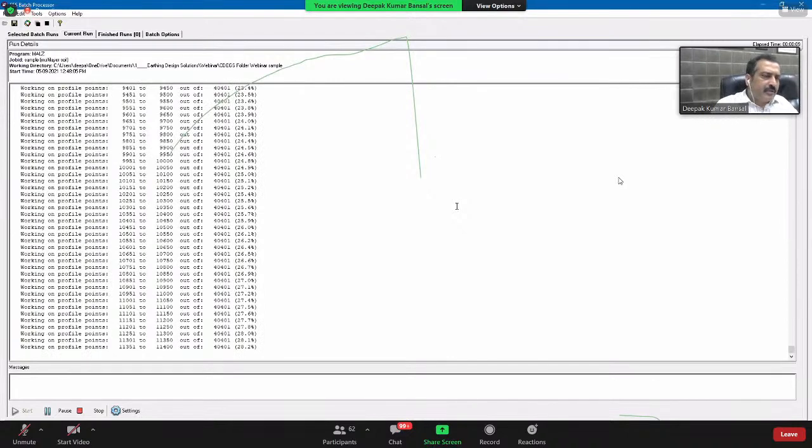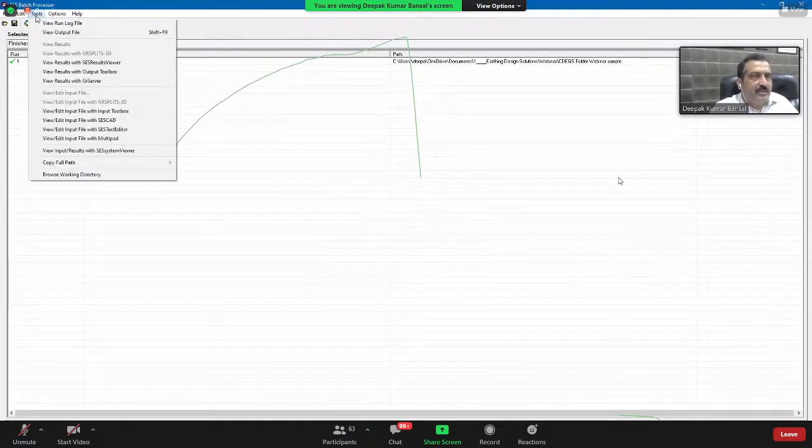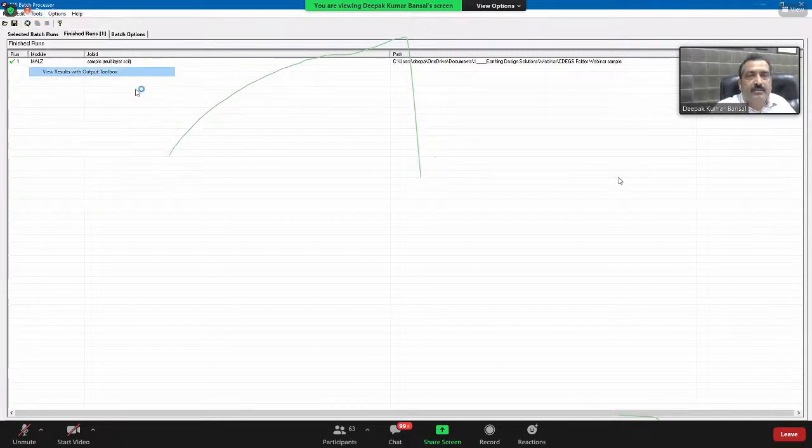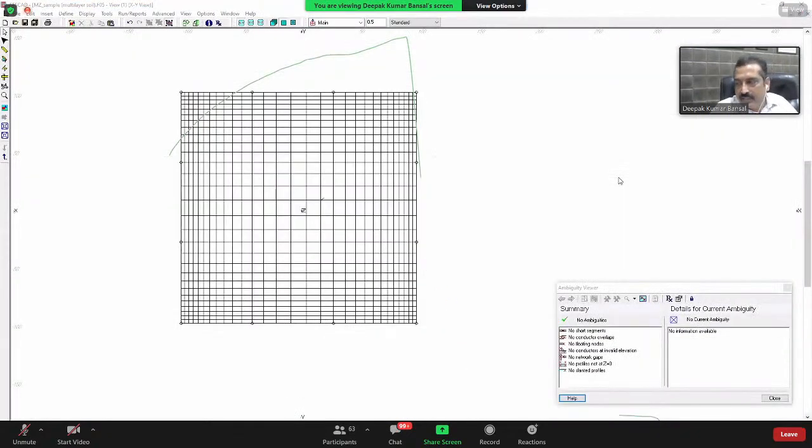So I just wanted to show you how much we can misinterpret if we don't do proper soil analysis. So two things are very important. One is the proper soil analysis, and second is the split factor, like the current division factor. That should be very correct. If we are using high current, then it may give us wrong results, and we may design an extra safe grid.